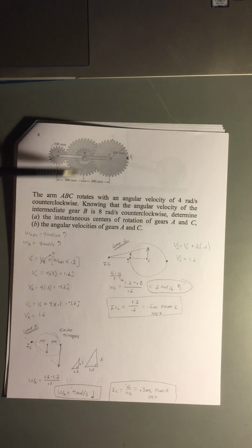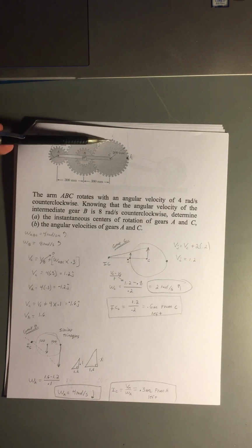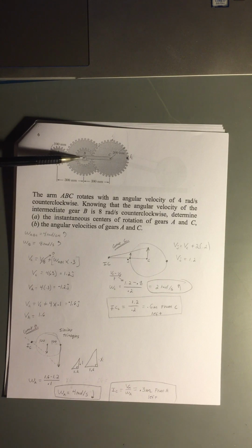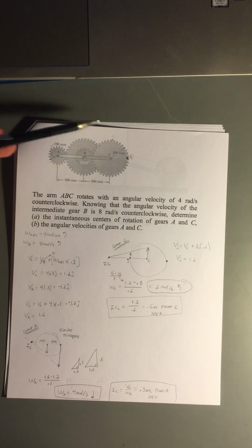And just looking at this diagram and thinking it through, we know that if we draw the velocity of C, it will be vertical in the j direction, and the velocity from point B to C where they touch here will also be vertical. And so since all the velocity vectors will be parallel to one another, what we're going to have to do is draw two velocity arrows and then draw a triangle and use geometry like similar triangles in order to find out where that instantaneous center is.